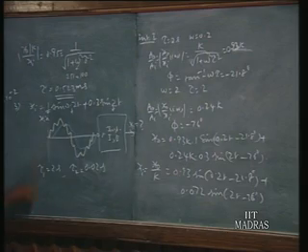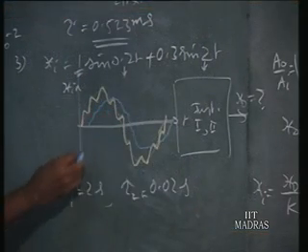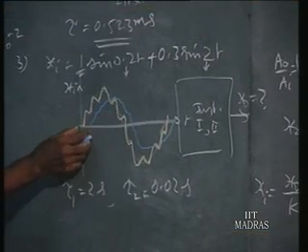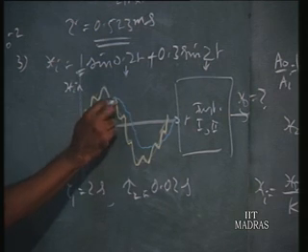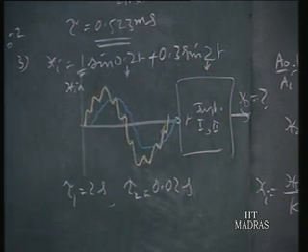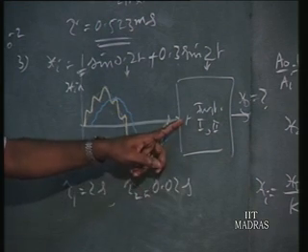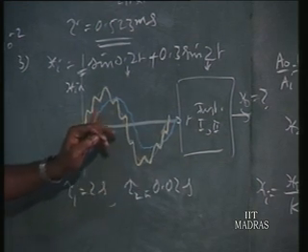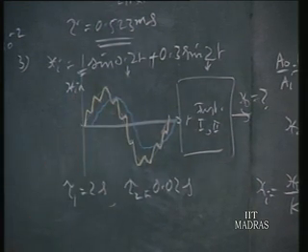So it is following, that is the high frequency component is completely eaten away. This is 21.8 degrees, later it comes, and this one it has reduced to 0.93. That is, the first instrument responds only to the low frequency signal, and for the high frequency signal it produces only small ripples, it is completely eaten away.